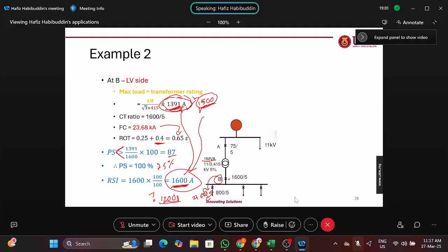So for that reason, you can use this equation, greater than. But then again, it is your transformer. You know the operation of your substation, your load and everything, the standards to be used, the guideline. So you decide whether you have a setting that is suitable for you. It is your own transformer, so you decide whether to allow for overload or not.